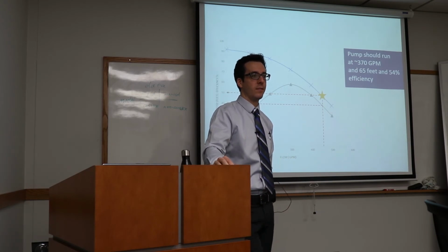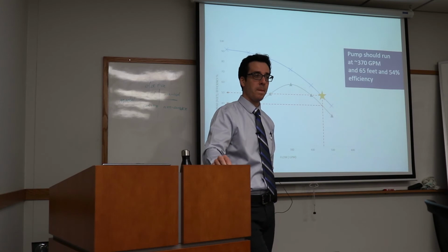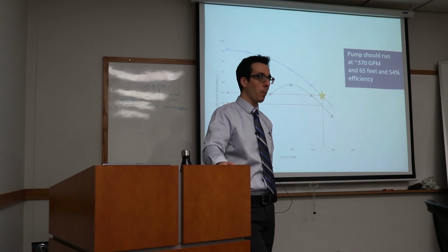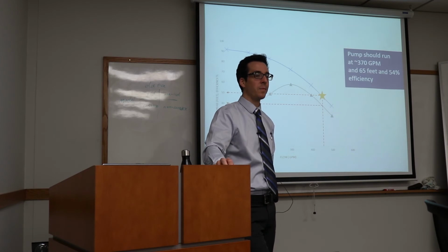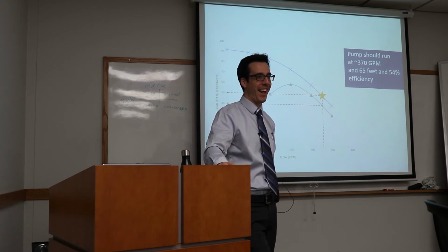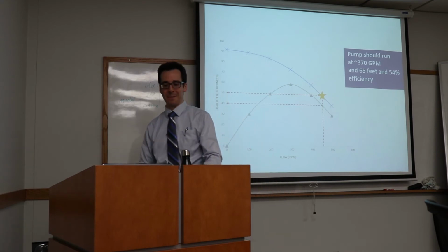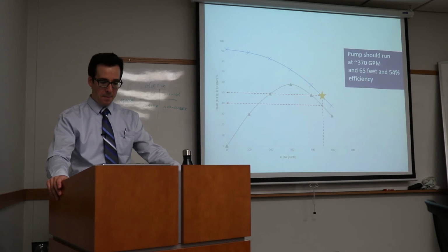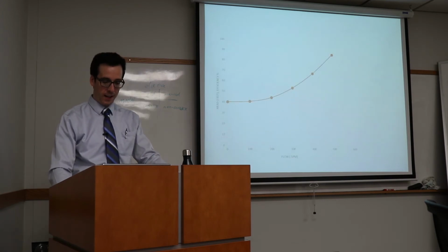The system curve. Well, the pump curve's constant. We could have got the wrong pump. Okay. But you're right. So is it more likely that the pump curve information was wrong, or that your characterization of the system head was wrong? Our characterization. Right. So whose initials are on the first curve? That's who computed the system curve. So that's the person you fire because they didn't do it right. Maybe not fire. That's probably a little strong, but critique may be the best word.